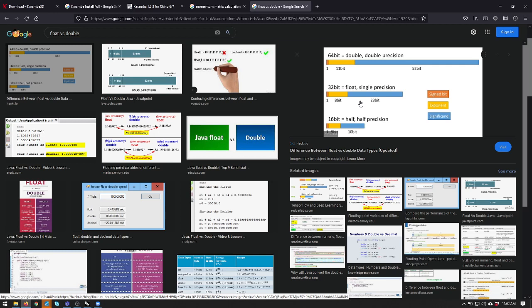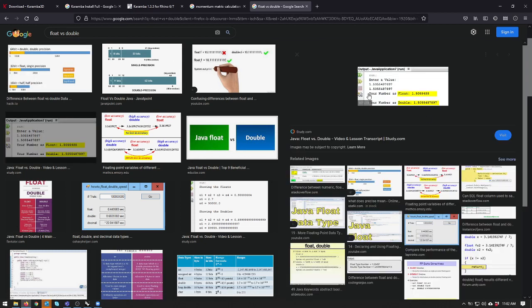Now that same rule, for the number of digits for a float or a double, applies to strings as well. So what that particular panel is telling you is that Grasshopper can't render the string that you're asking the panel to represent, because it's got too many characters in it for that string to be able to do its job. Does that make sense? Sort of.